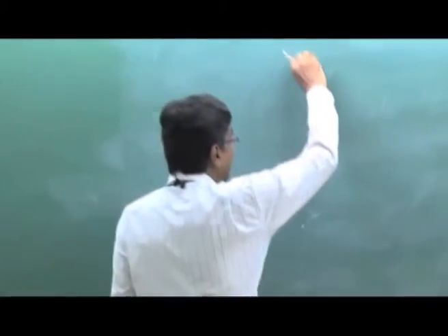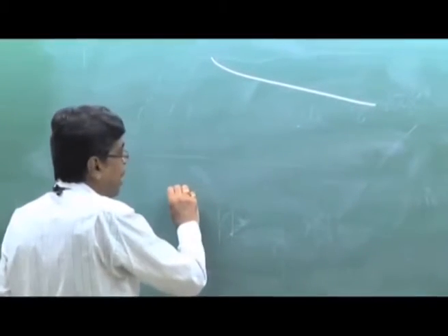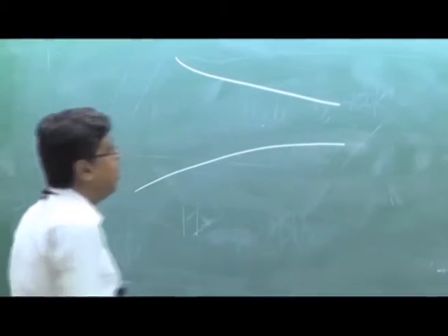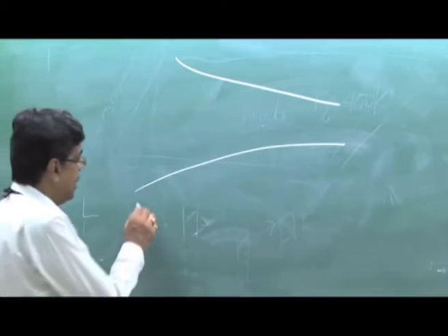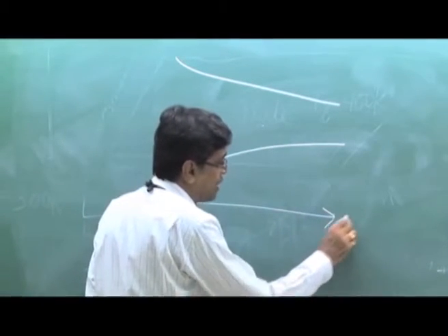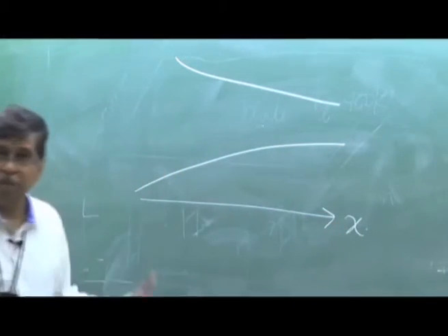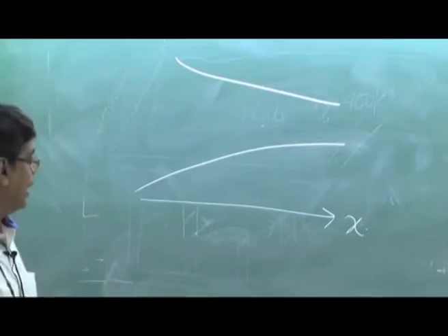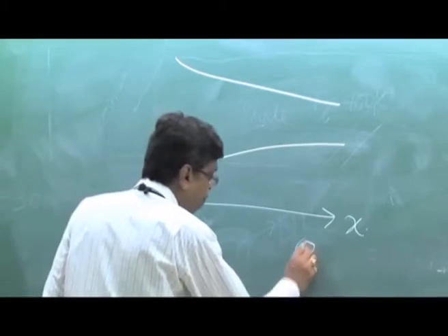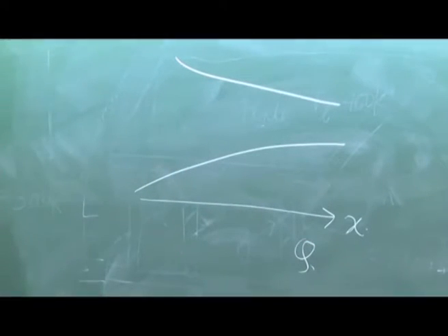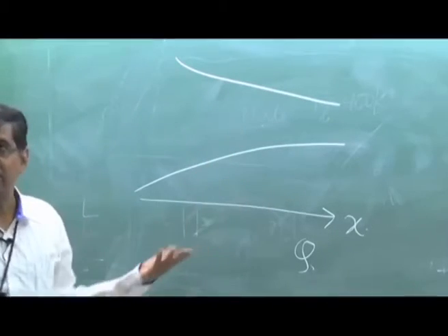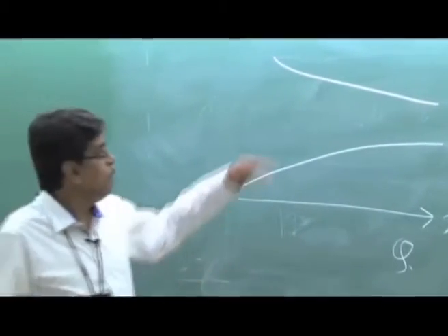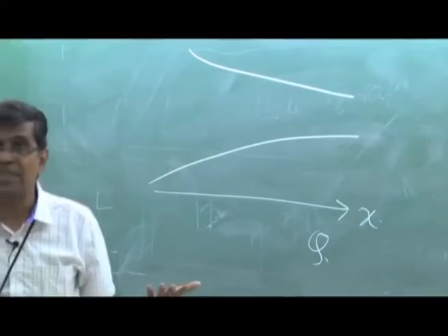If you consider a variable area wall and take this as the direction of heat flow x, which may be x, which may be r, whatever may be, I am denoting it as x, where the heat flux is there, which may not be the same at all sections. If heat generation is there, we cannot say so. If the lateral convection is there, we cannot say so.